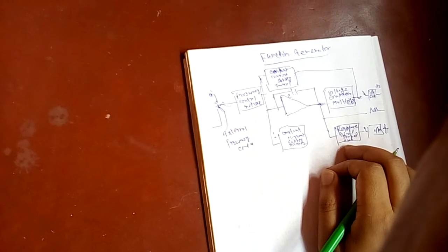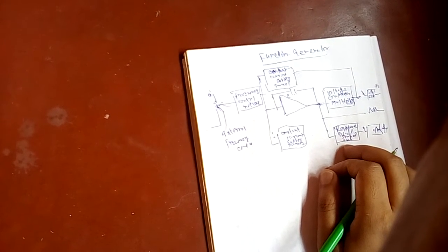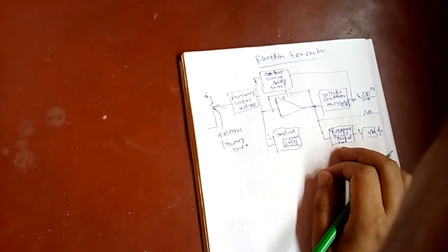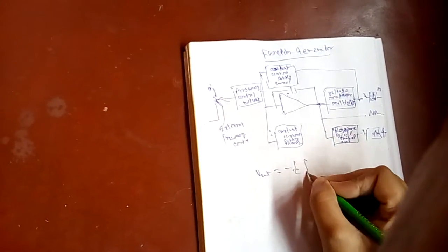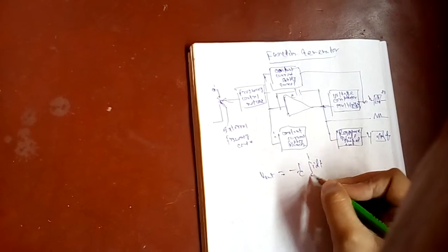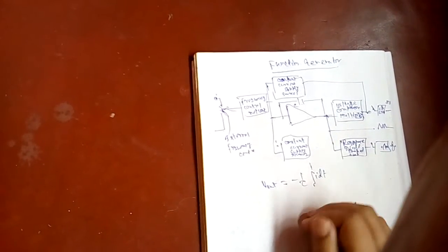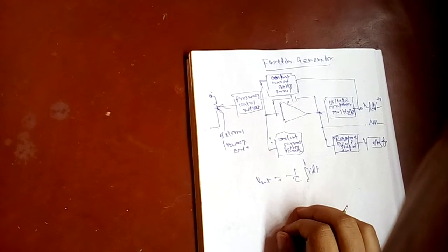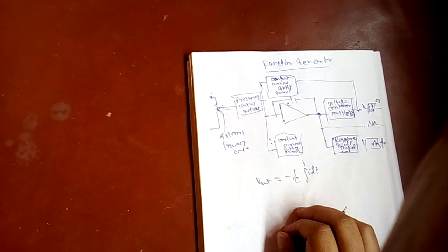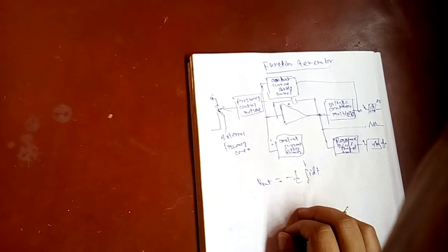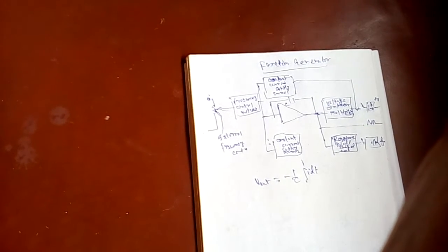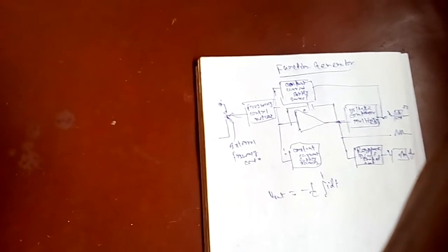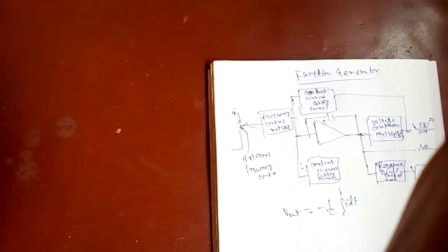For frequency control, a voltage regulator controls the two current supply sources I1 and I2 we have discussed. We know the output of an integrator: V out equals 1 by C integral of i dt, from the op-amp circuit where C is the feedback element. Increase and decrease of the current increases or reduces the slope of the output voltage and controls the frequency. Then it is connected to a voltage comparator.